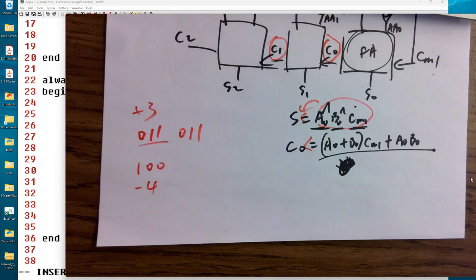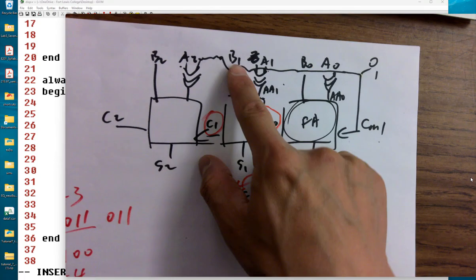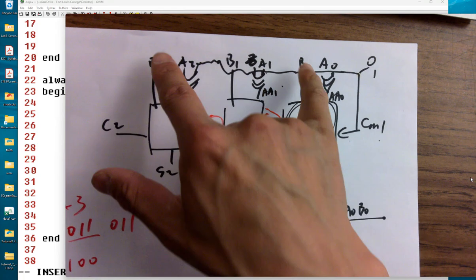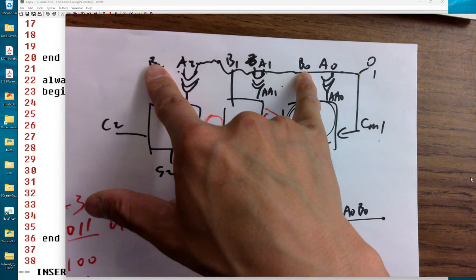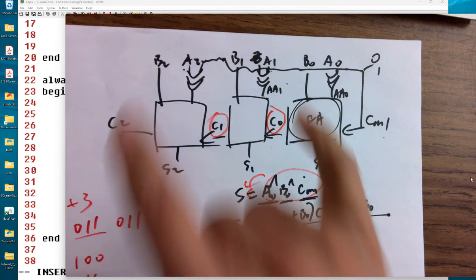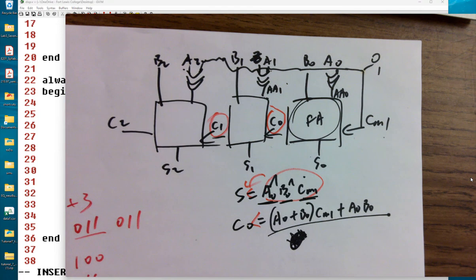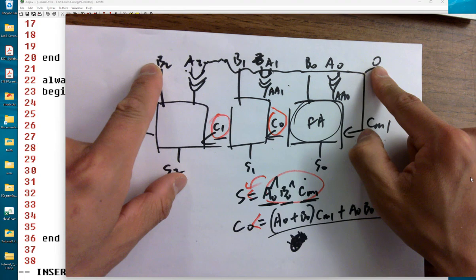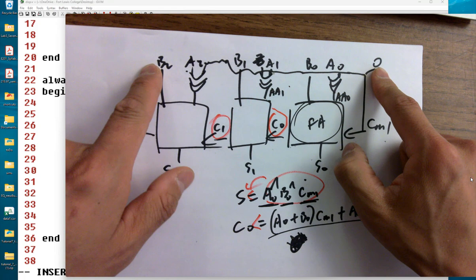But is it possible to get a -8 as a result from the adder or subtractor? Probably not. -4. But how do you put a -4 for the B's? Since the B's doesn't have an actual gate, you're not flipping that. Oh yeah, I guess so then. Oh, you can, because if you put 1 0 0 it will be -4. It will be -4, 1 0 0, and then 1 0 0, and you put this one to 0. Should be a -4.